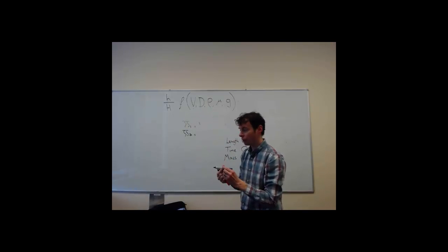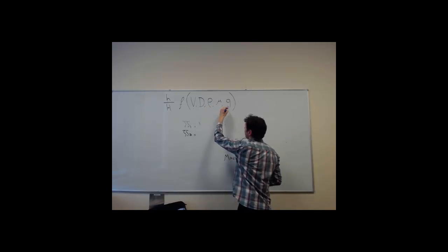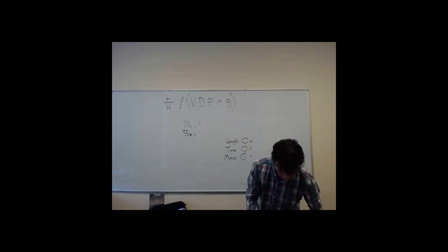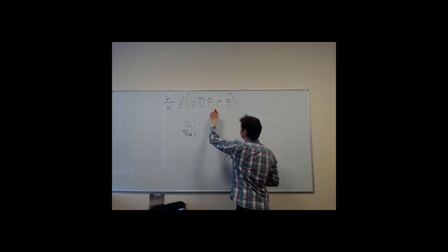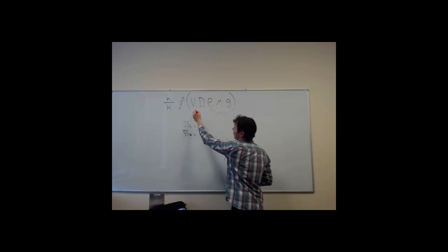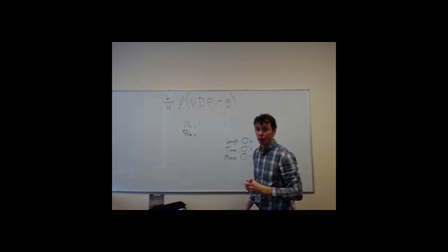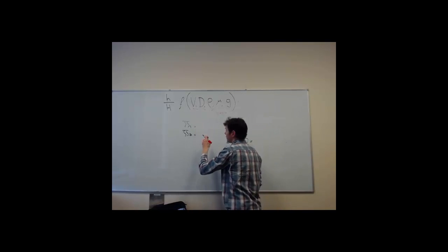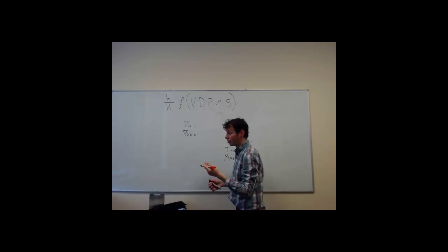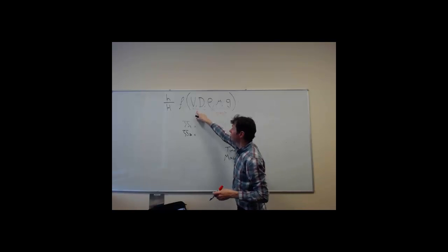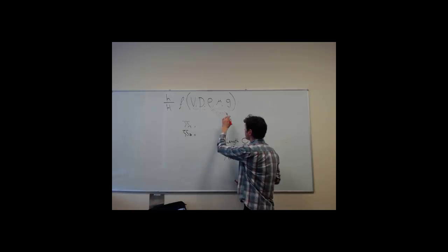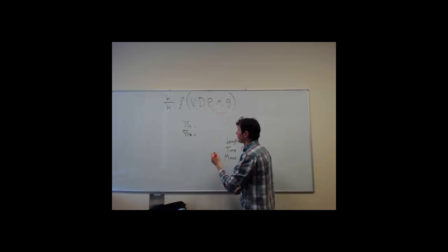Right, so this time round I'm going to sort of invert the problem. I'm going to repeat these ones. I'm going to fix velocity and diameter. So I'll just go halfway through the Pi1 group and you'll see what I mean by choosing parameters. So to try and measure the dynamic viscosity of a fluid is not particularly easy. Far less easy than, for example, trying to work out a velocity or a length. And the same with the acceleration due to gravity.